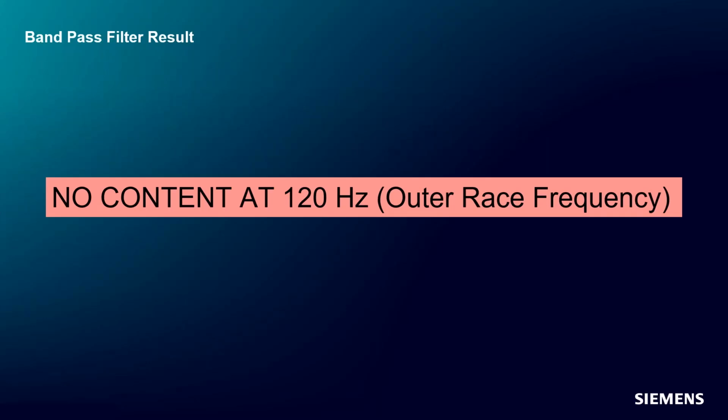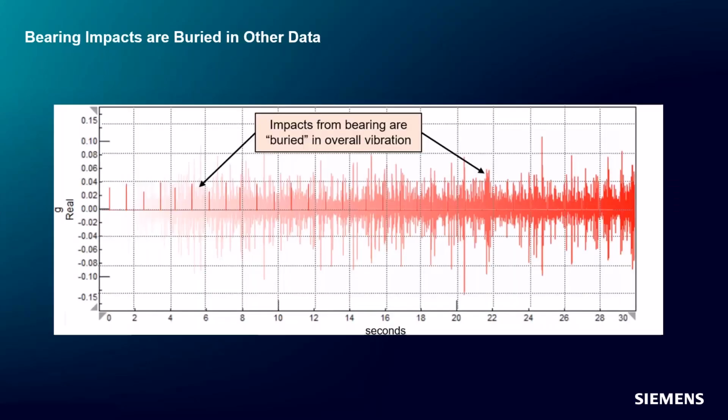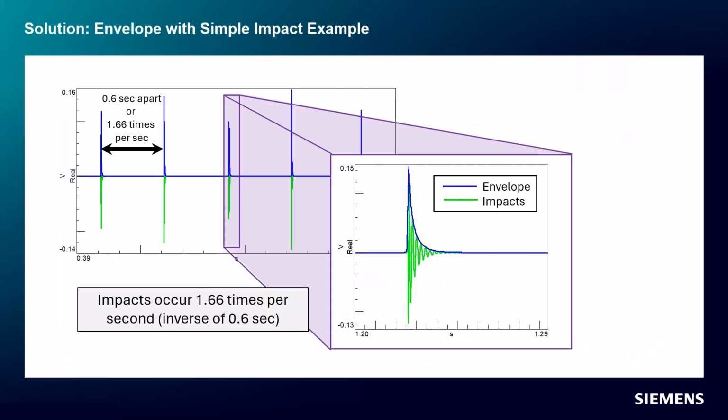We could envelope the time signal. That's a very good guess. I think you might have been reading ahead in the notes there, Steph. Yeah, an envelope is one of the keys. And an envelope is not just something you can use for bearing analysis. You can use it for doing things like modulation measurements, and there's a lot of other things.